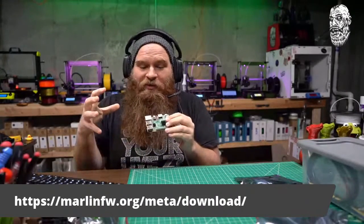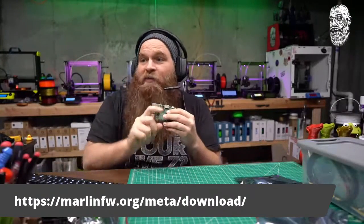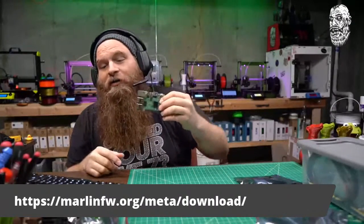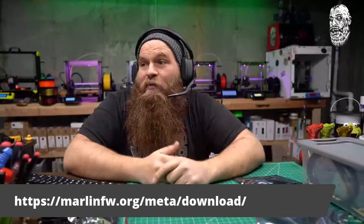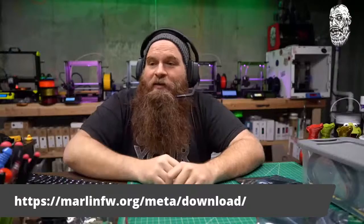Basically all the curves and movements are calculated ahead of time in here, and then the movements are just sent to the printer. So the printer can run more efficiently because something is handling all of the hard work before it's sent to it. You can make an 8-bit processor board like a Melzi work way better. You're no longer limited by the space. Whatever you can put on here, you can make run on Klipper.